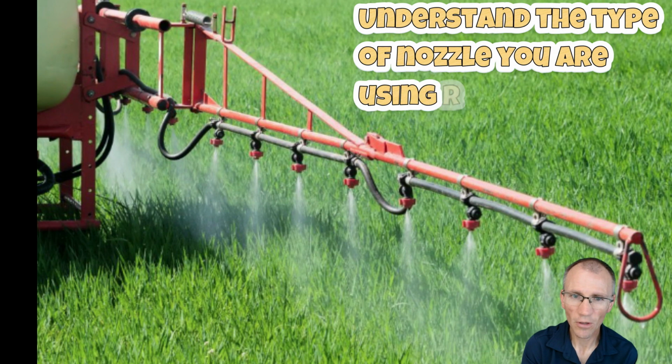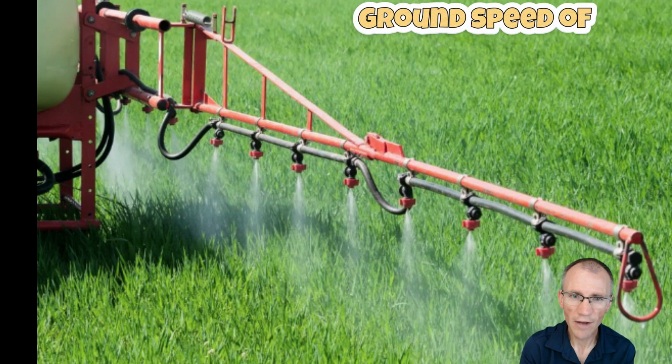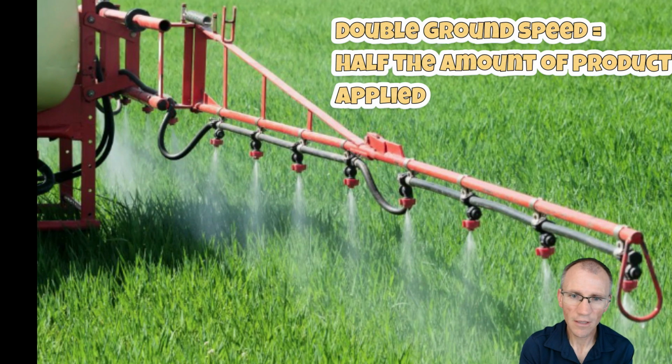Now, we talked about this earlier. There's a lot of different types of nozzles you can use, so that's a whole other ballgame. You have to understand the flow rate of each individual nozzle to understand how much of the product you're going to put out. Now, as far as ground speed of the sprayer goes, there's another one. If we're moving 1 mile an hour or 2 miles an hour or 3 miles an hour, whatever the case is, if we start moving faster, we're going to be putting out less. We talked about that down here at the bottom of our last slide. Obviously, if we double our ground speed, the sprayer reduces the number of gallons applied per acre by 1/2.